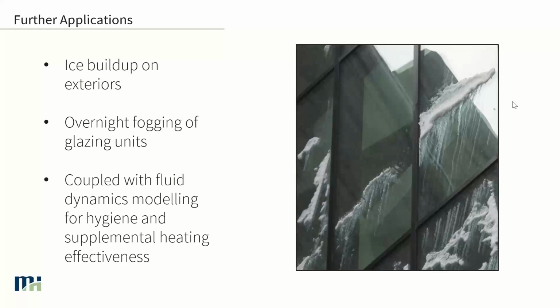Similarly, if we're starting to get more triple glazed units, especially on higher end homes or higher end projects, we get worried about what's the risk of fogging on the outside of the glazing units, right? Are we under the right conditions where that can occur quite frequently, and are people going to then blame the supplier, saying, oh, something's wrong with my windows, I can't see out of them in the mornings?